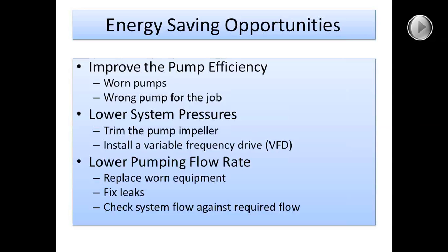What these guys did, they decided they wanted to save some energy, and so they just quit using their booster pumps, and they operated the system at lower flow rates. And so the system was working okay. All the pumps were running, and they were giving them the pressure they needed for the amount of the system that was operating, and that seemed to be okay. But we calculated pump efficiencies, and the efficiencies were really low.